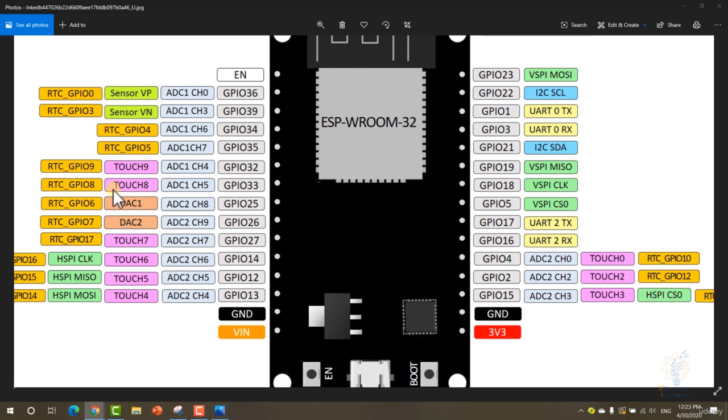So the total range of the analog to digital conversion readings can go to 4095, or 0 to 4095, instead of 1023 on Arduino and ESP8266, when a maximum of 3.3 volts is applied to its input. So you can expect more values that can go up to 4000.